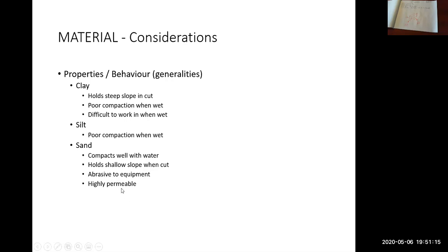So if you dig a trench deep enough in sand, you're going to get groundwater coming up. Your trench is going to be wet, and you're going to have to pump it continuously in order to keep the water out. As it gets wet, it's going to fall in on itself. So water and sand in the ground is challenging to deal with.